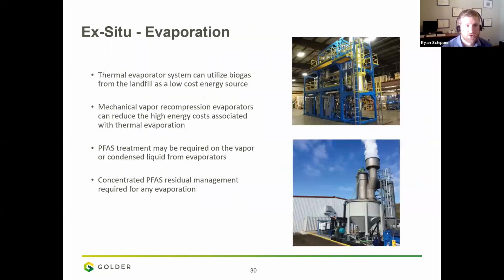Evaporation is an ex-situ option. Thermal evaporators can utilize biogas from a landfill. They can also utilize waste heat or other low cost energy sources. In the picture here, the lower picture shows an evaporator discharging to atmosphere, where we could have some issues with the precursors being volatilized within that stream. The upper picture is a mechanical vapor recompression evaporator.